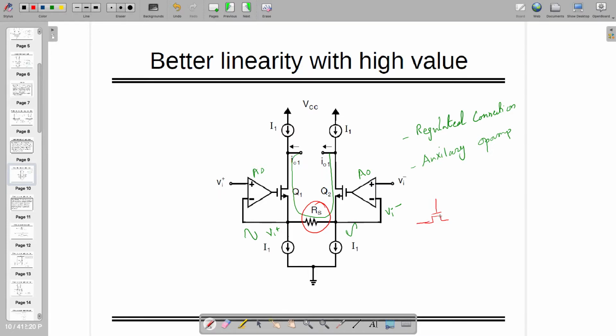If I'm connecting these connections, let's call this point A and this point B. If I connect them in such a way that the resistance with respect to VAB, or maybe some input voltage, is linear, this is only possible if I make this transistor operate in the triode region, right? In saturation, it's saturated, right?